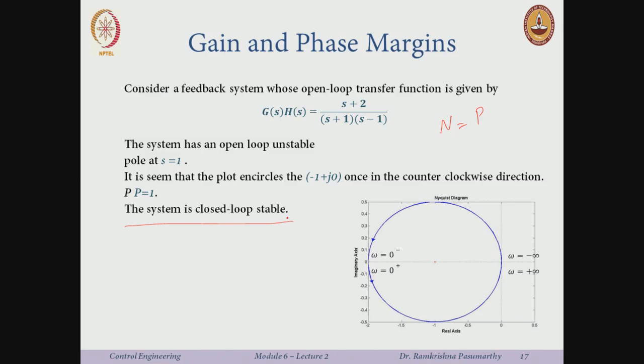Okay. Now, what is the gain margin? We had said gain margin is the reciprocal of A. How did we define A? A was defined like this. This was A, this was the point minus 1 plus j 0, 1 over A. Which means I am looking at the intersection with the real axis. See where this intersects the real axis. It intersects here. What is the magnitude? Well, it is 2. Now, is the gain margin 1 over 2? Well, we will see what that means.